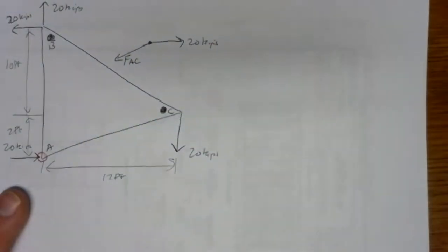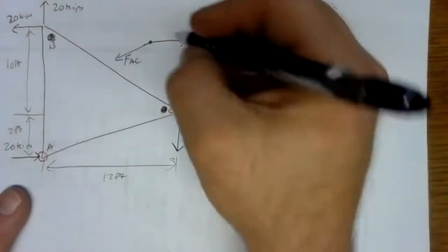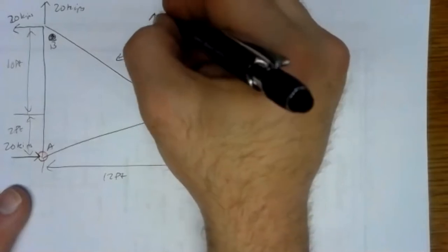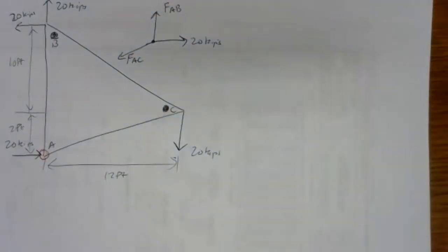And now that you've kind of convinced yourself of that physically, it makes it a little easier to figure out AB. The only way this could still be in equilibrium with the forces drawn as they are is if AB was up. So that looks like equilibrium. We've got a tug of war, no one's winning.